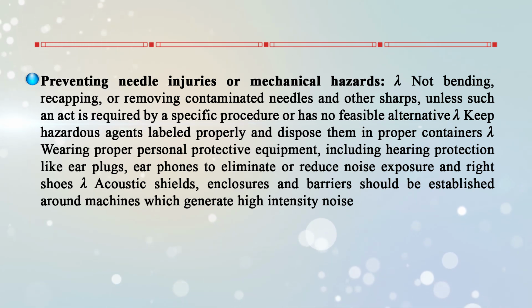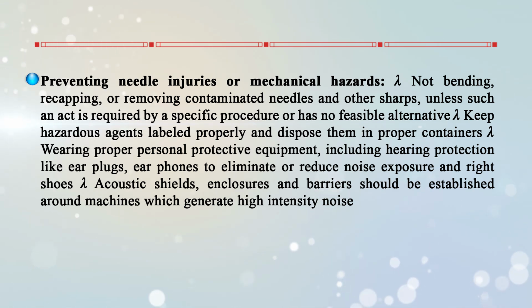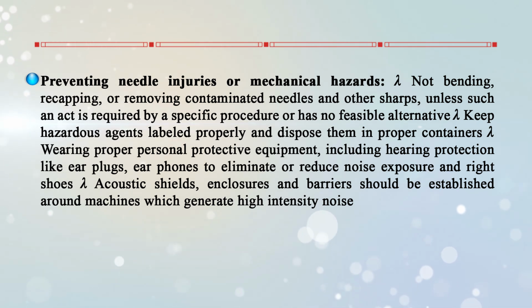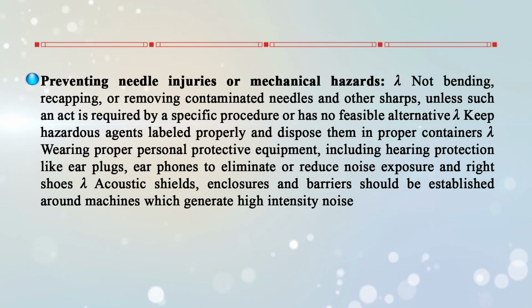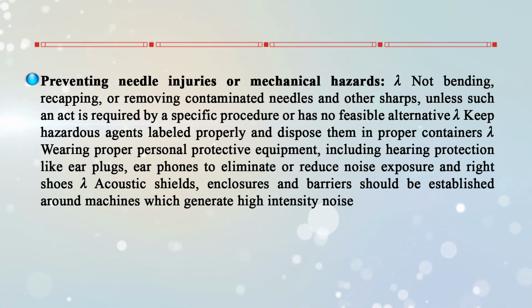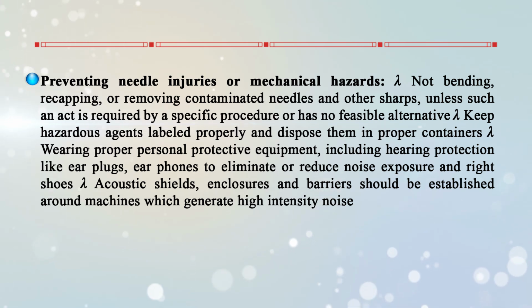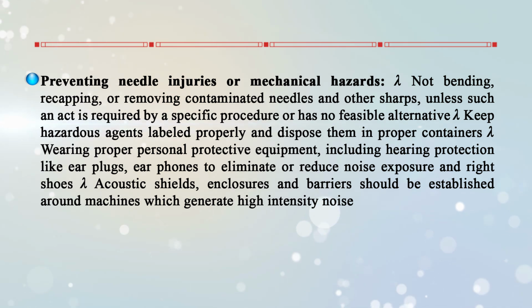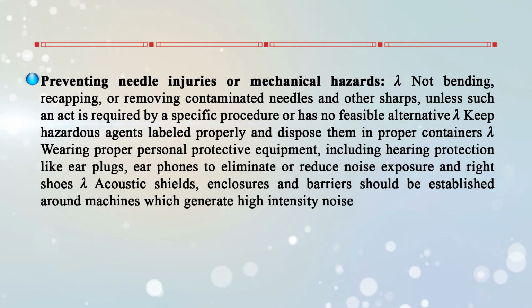And they have to keep hazardous agents labeled properly and dispose of them in proper containers, and wear proper personal protective equipment. And also if noise is very high, acoustic shields have to be used, and enclosures and barriers should be established around the machines which generate high intensity noise.